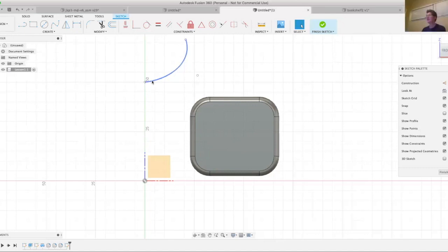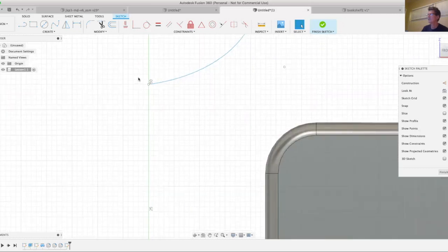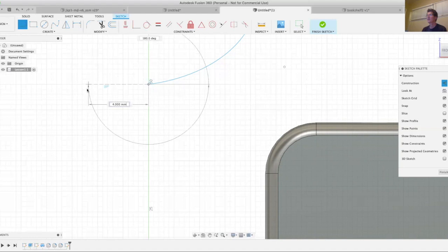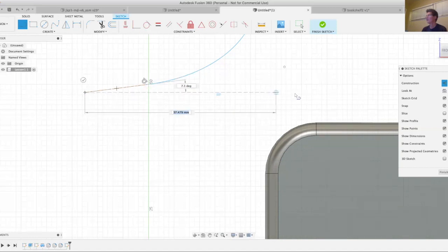But you can control the angles at the end by what you're doing with lines there and specify angles. Actually, or you can at least go perpendicular. You can use a construction line if you need to, but what you do is you create a line which is tangent. So you see the tangency there. Yeah.